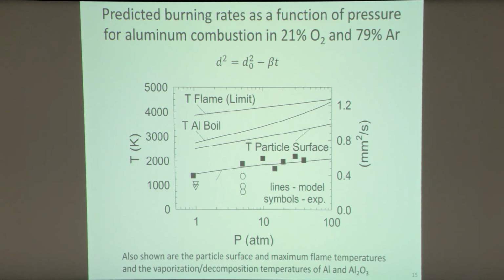Okay, and from those measurements, one can also get burn rates. In a diffusion mode of combustion, one should expect that the burn rate should be relatively independent of the pressure, because if you have studied combustion and droplet combustion, and there are some notes at the back of the note, you'll find that the burning rate scales with rho, the density, times the diffusivity, times the log of 1 plus the Spalding B number.